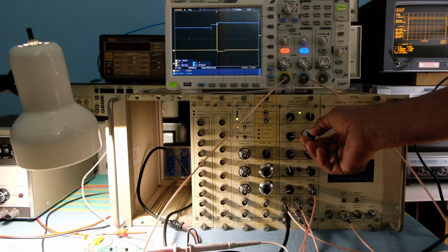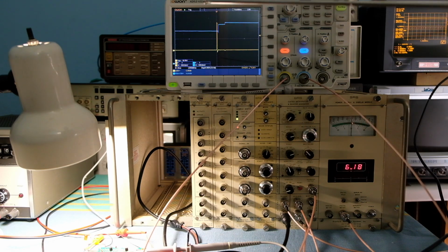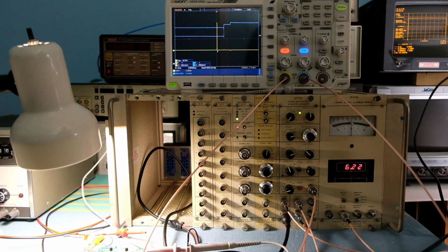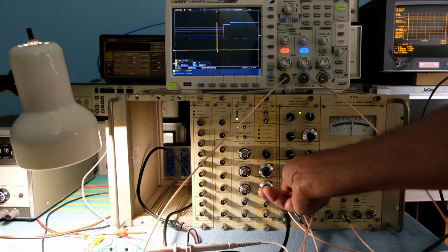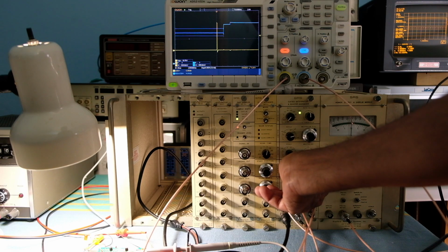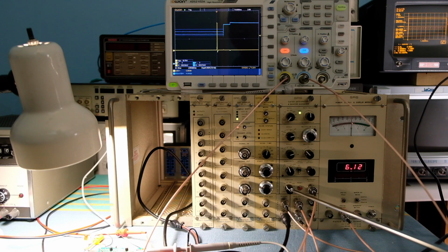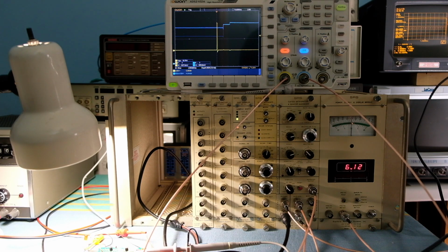just before the reset comes on, as you can see, it's got a lot of variation because of the 60 Hertz interference, but this voltage is reasonably stable. And if I move it further away, you'll see it becomes a little bit better. Without any averaging, it's going to look a little bit noisy, but I can improve the stability of the signal by filtering out even more by averaging. With the averaging turned on to about 10 samples, I'm seeing a fairly clean 6.12 volts or 6.14 units from the boxcar.